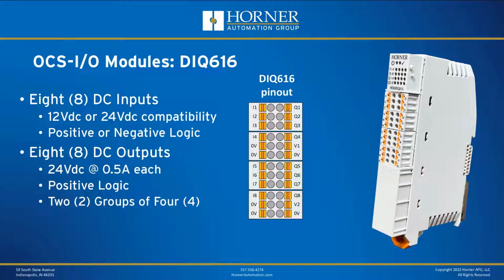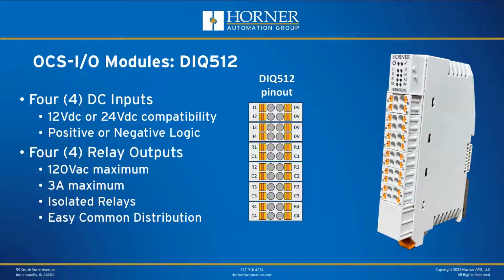That is an 8-point DC input, 8-point DC output card, which is on the input side compatible with both 12-volt and 24-volt systems. It can be used in both positive or negative logic systems. On the output side, you get half amp 24-volt outputs that are positive logic in 2 groups of 4. So I imagine this will be a pretty popular module for digital I/O, as you'd expect.